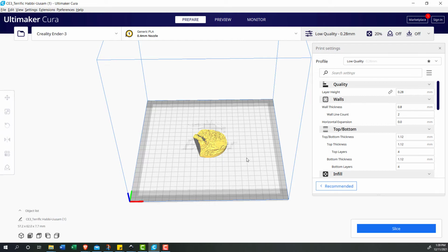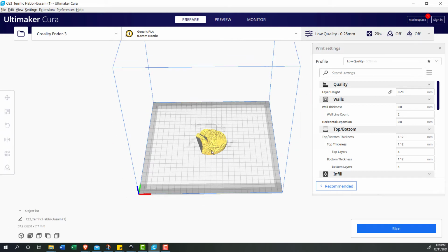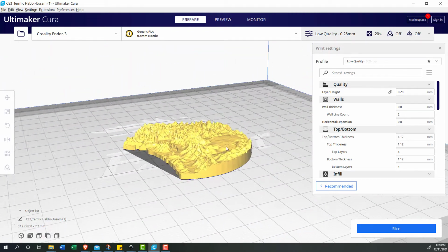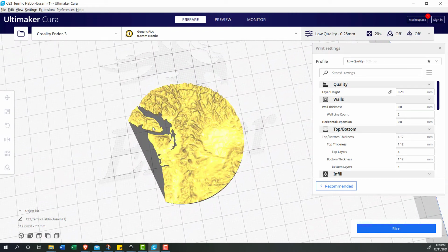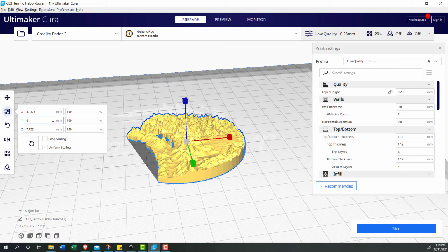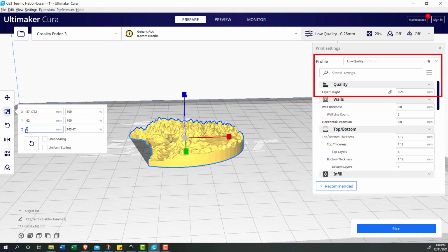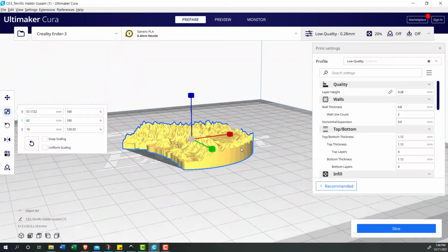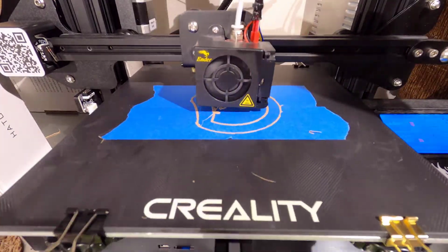The last step before we start making the actual design is prepping the file for 3D printing in your preferred slicing software. My preference is Cura. Of note, here you can scale the object to meet the final dimensions you want, in case dimensions were altered in the previous steps, or you want to change the height. You can also print at a pretty high layer thickness, as I personally don't think that thicker layers detracts from the final design.